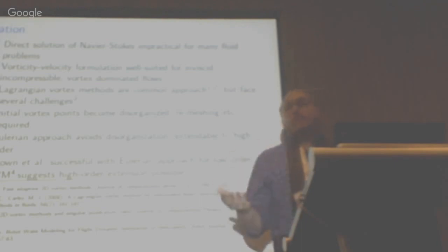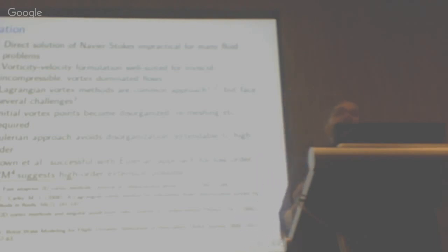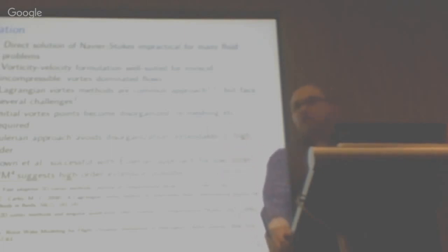So ultimately, how do you go about simulating this? So it's challenging because when you think about the multitude of scale in the problem, the characteristic length is the size of the wind turbine blade. But downstream wind turbines are 20 or 30 blade lengths away. So it's quite a bit of distance relatively. So when you try to simulate this, you want to make sure that you are capturing the important features of the flow and that you're not smearing them out because it's traveling quite a bit of distance. So if you're dissipative, you're going to have problems. Similarly, if you're not explicitly conserving the quantity of interest, in this case vorticity, then again, you may have simulation challenges there. So, if we had the world's most powerful computer times 1,000, we'd do DNS and who cares?